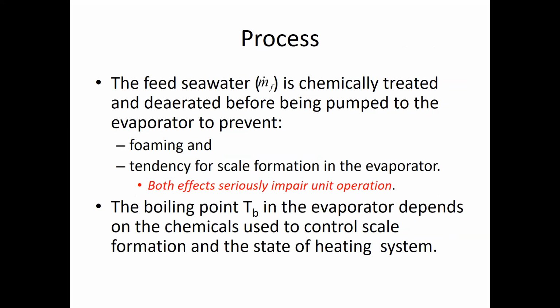How much feed is coming, how much water that we need to take from the sea. This water needs to be chemically treated by anti-scaling agent, anti-foulants, anti-foaming, so that you can just eliminate or at least reduce the effect of this kind of problems in the system. The salt effect becomes more significant as the temperature increases.